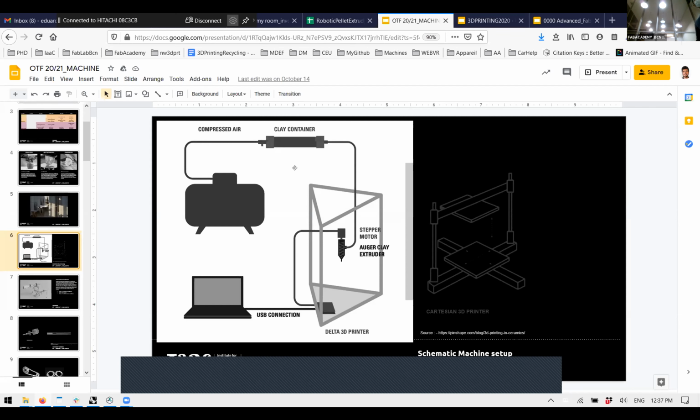In this case, we are using direct cartridge printing. We have a small compressor here, and a manometer to regulate the pressure. What is the pressure? You always need to test based on your mixture. You always start with lower pressure and start testing. For example, right now the pressure is on, but I don't see material coming out. So I slowly increase the pressure, and the material is going to go faster or slower, and I release and stop.